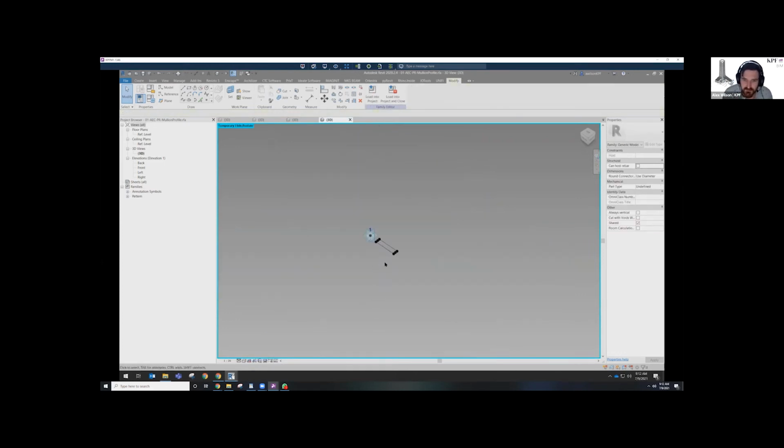So when I need to create a profile, I'm going to do that within another adaptive family, just a single pointed adaptive family instead of a 4-point, because it's just a profile. When you are placing points, there's a couple of ways. If you're just making something really simple, you can set your work plane. Using your WW keyboard shortcut, you can see after I do set work plane, I can then snap to any of these. Now, because it's going to be a horizontal profile that's swept around the exterior, obviously I want to set it to this one. And then from here, I can just sketch.